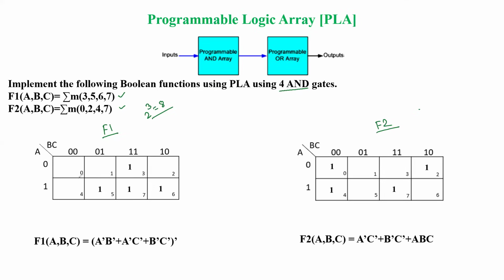So for function F1, we are going to take the complement. For the min terms that are not given, we write 0, so that we can take the complement of the function. Once this 0 is marked in the K-map, we have to make the combinations, whether a pair is possible or what is the maximum, better combination available.